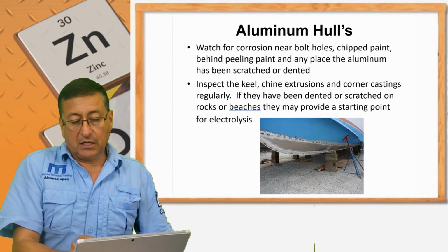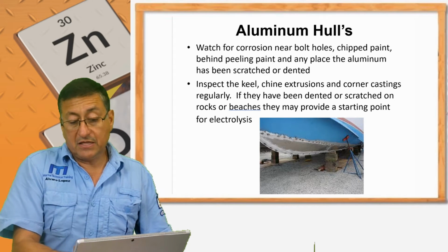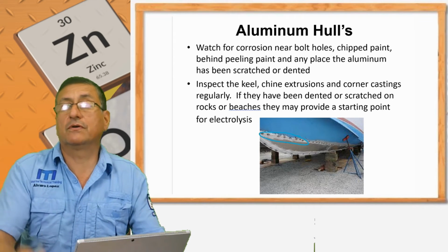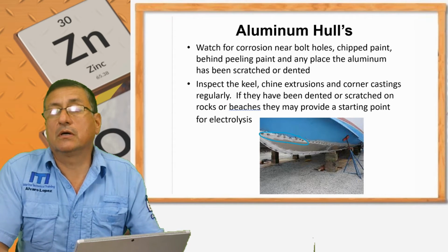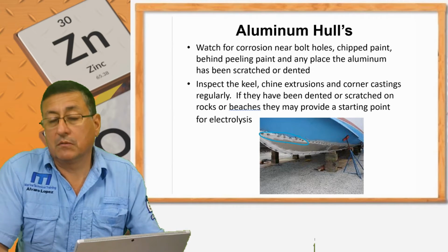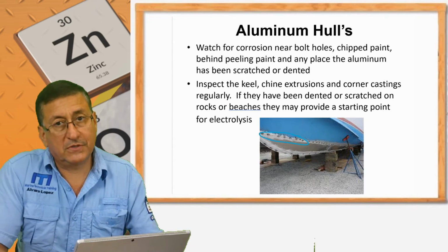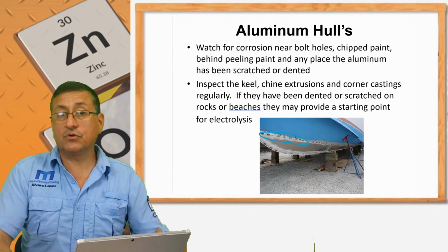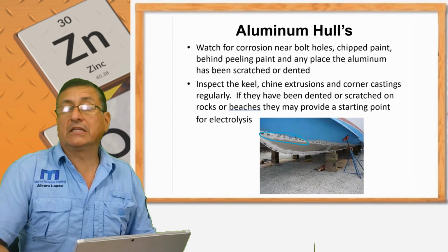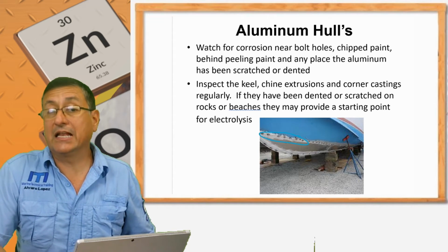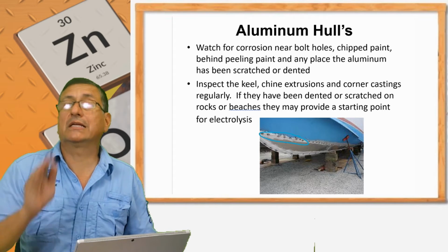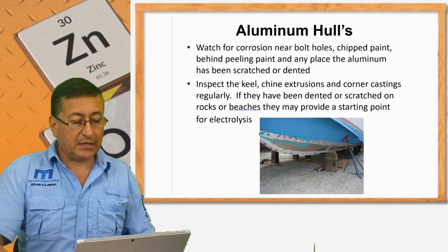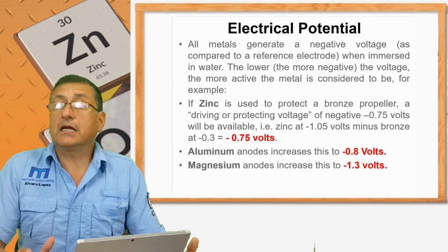Yes, especially when people replace the bottom. It's possible to replace the bottom completely or repair sections of the bottom of the boat because it's aluminum. And once again, if you are a good welder, okay. If not, call a good welder. If you use inappropriate materials, you can accelerate the electrolysis in that area. For that reason, the selection of the welding material for that area is critical. It's very important.